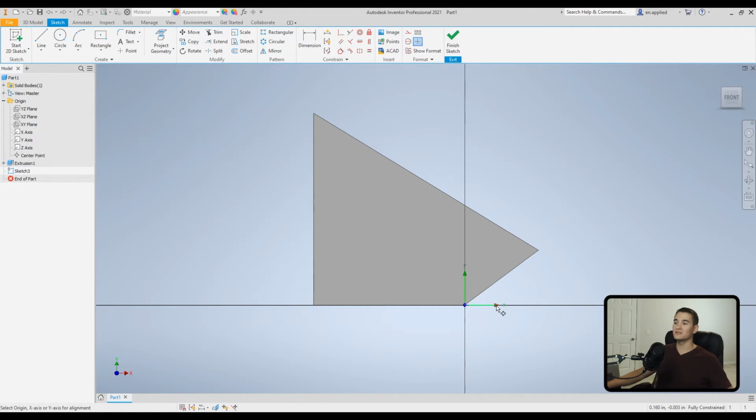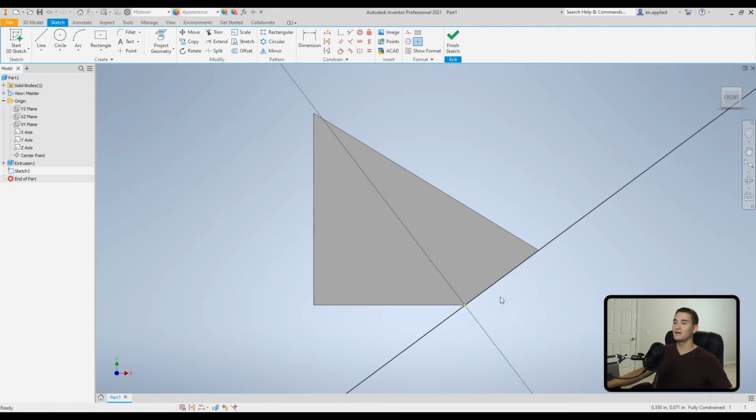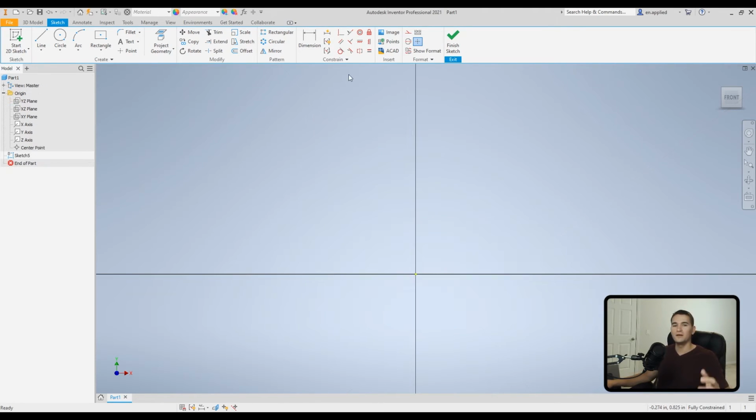So what I do is I click the little red leg, which is the x-axis, and then click this part feature here on this angle. So we'll click that. And now you'll notice the x-axis is in line with that. And then if we go to OK, the coordinate system has shifted to now be in line with that. So this is really handy if you're trying to create some eccentric geometry that is referenced off a different set of origin directions.